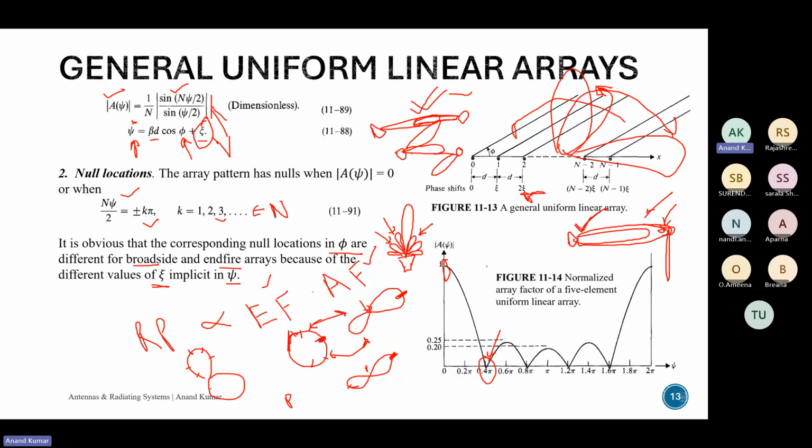I haven't done it, but it does seem possible, because the array factor is essentially multiplied with the element pattern. So if you could engineer null locations inside the radiation pattern by rearranging your array, which means you are modifying your array factor to have different null locations in your pattern, then by varying the null locations you could essentially engineer creating lobes in your array pattern.